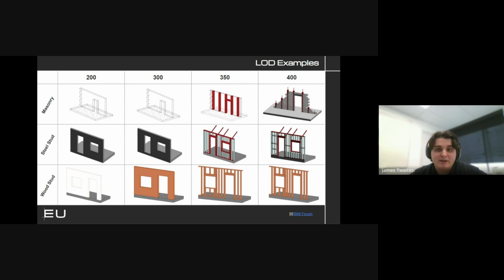There are some common pitfalls that affect lots of projects, which are things like overpromising, and that's a problem even if they do deliver to the promised level. If someone is requesting or offering LOD 400 information, and you're 6 months away from having an IFC design, you need to ask yourself how that information gap is going to be filled and whether those necessary assumptions will hold up as the project progresses. And then secondly, an issue that gets run into a lot is clash testing before the prerequisite LOD is available. So there are some aspects of coordination that can't be done before a prerequisite level of development.